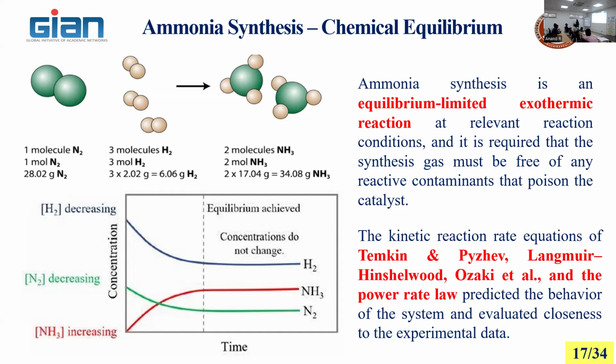So the hydrogen will be adsorbed on the catalyst's porous surface. We need to ensure that the desorption of the adsorbed hydrogen happens frequently. Otherwise, some pores will be closed, and it will affect the ammonia formation. So we need to ensure that the regeneration of the catalyst happens at a particular temperature and under pressure. Regeneration is a very important concept for ensuring the yield of ammonia.